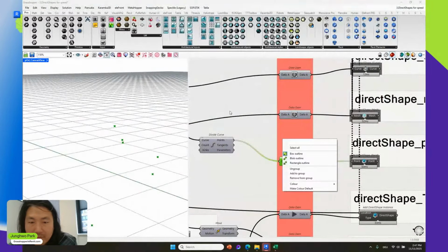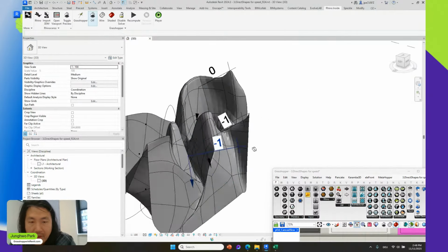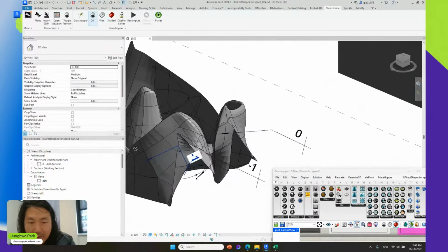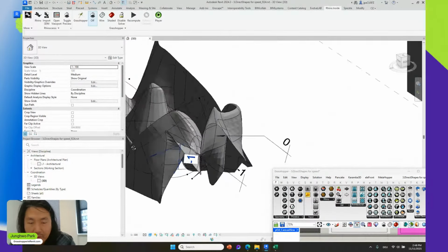And now if I, let's say, change more points, the more points will basically create more elements. And in this case, if I again shoot these points, then it updates, but you can see those spot elevation annotations are remaining, right, as they update to the new position. As long as you don't delete them, they are always going to update.